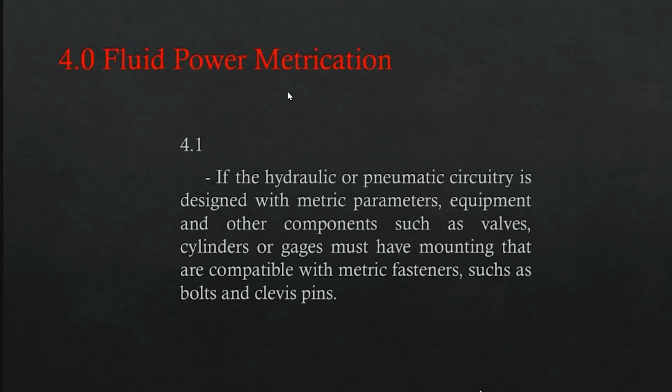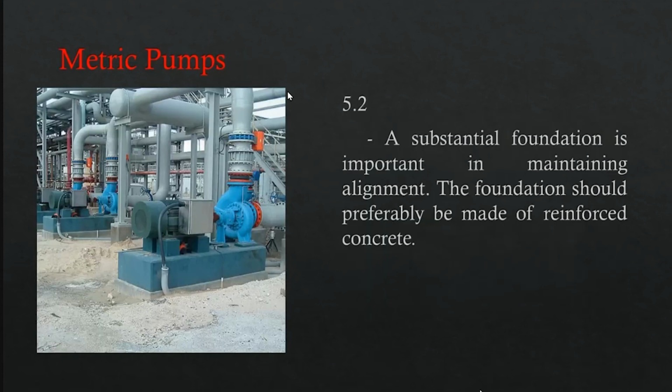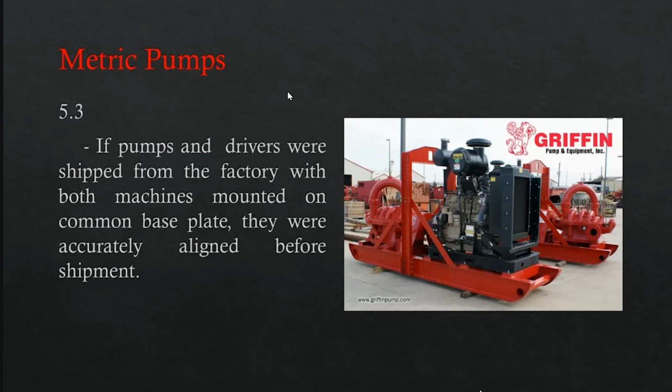The fluid power metrication. If the hydraulic or pneumatic circuitry is designed with metric parameters, equipment and other components such as valves, cylinders, or gauges must have mountings that are compatible with metric fasteners such as bolts and clevis pins. Pump foundation and alignment. Pumps should be installed properly. A substantial foundation is important in maintaining alignment. The foundation should preferably be made of reinforced concrete.